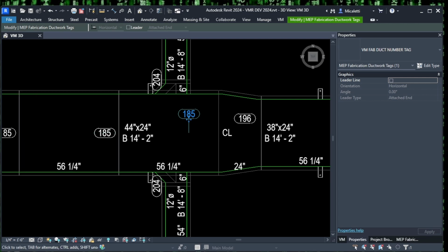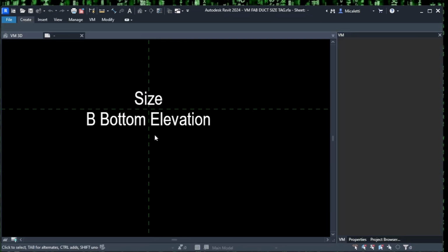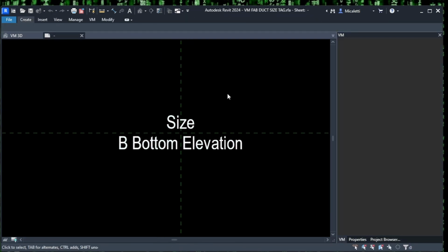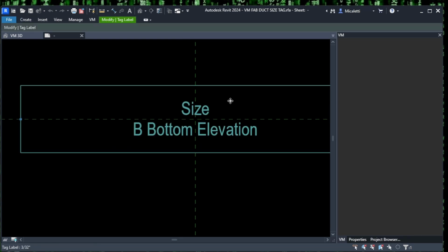There's a few other rules. It has to be a single type family. Also, when you're making these, it's a good idea to start with one of the default ones and customize from there, at least until you get the hang of it. But you do want to make sure that's a pretty minimal change. But yeah, I think all of ours or most of ours are multi-type families. Yeah, and that's fine.